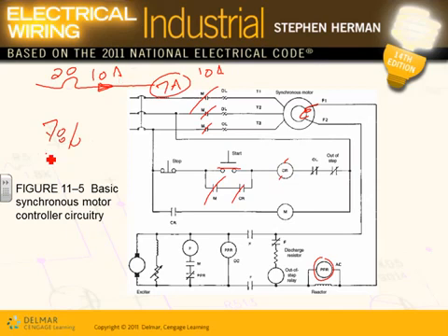So if this becomes 100% power factor, and your motor is 7 amps, then you're pulling 7 amps, and you're good to go. You don't have to pull 10 amps to run a 7 amp motor, roughly. Does that make sense? That's the difference between 70% power factor and 100% power factor on a 7 amp motor. So if it's 7 amp, you pull 7 amps and you're good to go. Does that have an effect on the motor itself when you're pulling that much? The motor is the guy who is creating this. No, the motor itself wouldn't be affected. It's a voltage drop problem.